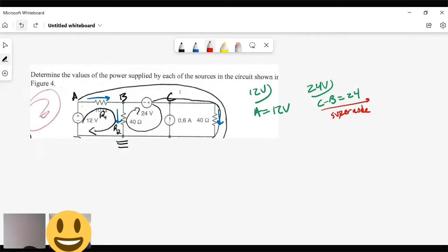So once we hit that situation, we got to do step 3, which is do KCL. We got to do the current law. Now, we can only do the current law on nodes B and C because node A is done. Node A is good. Like node A has been figured out. Put a little check on it. So what's left is B and C. But the thing is, B and C are both connected to our source. So that's going to be our supernode. Make some sense? So I'm going to put a bubble around it.